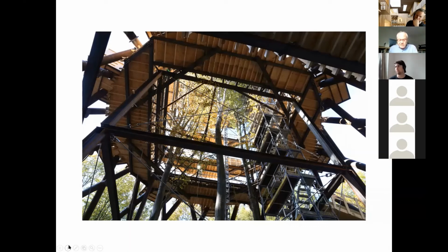We analyzed different erection methods and based on that created the final erection method statement. Our final conclusion was to construct a center-placed erection tower with a size of 9 by 9 meters in plan, to allow for the 3 existing trees to stay, which the owner wanted to save and be part of the visit experience in the tower. This is a completely traditional steel structure. You see the columns here of this temporary structure, and you can also see the 3 existing trees inside the temporary tower.